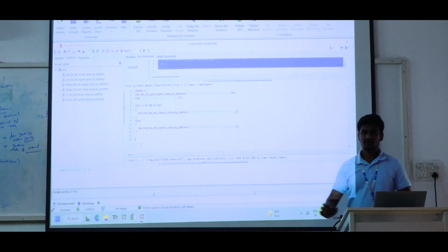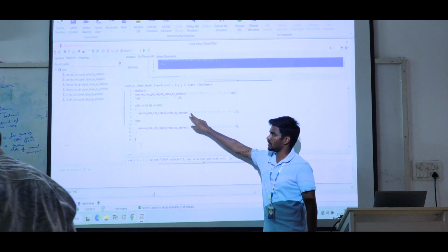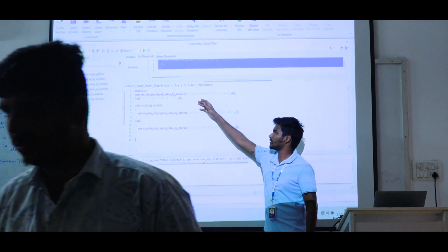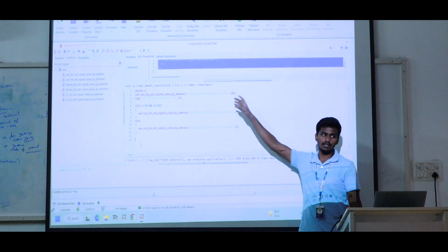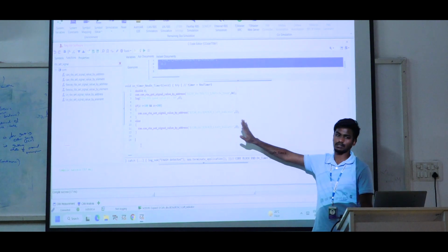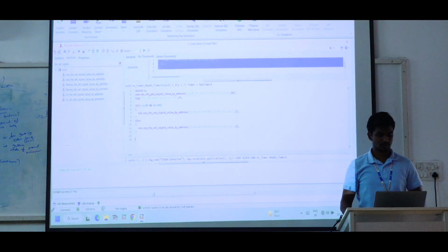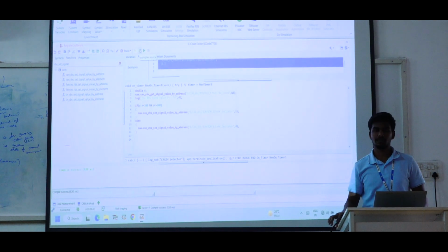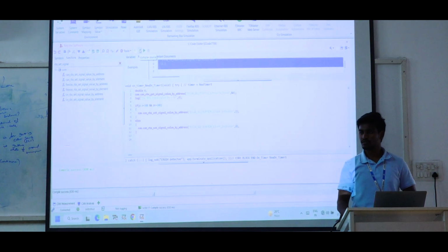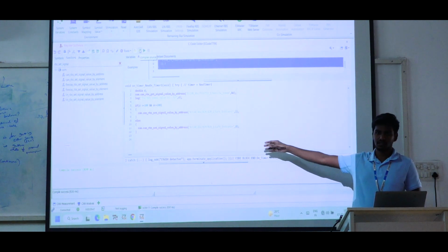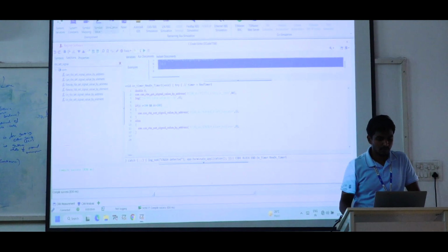Yes. So the same signal you have to paste in the if and then else column. Suppose the value is reached, you have to turn on the LED. Suppose the value is not reached, you have to take the value as 0. Okay. Parallelly, just compile now and then close this, not start that. We will add the indicator on our panel. We need to add it. So you just compile. If you find any error, please clear the error and then open the panel.